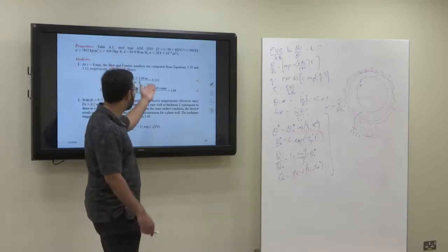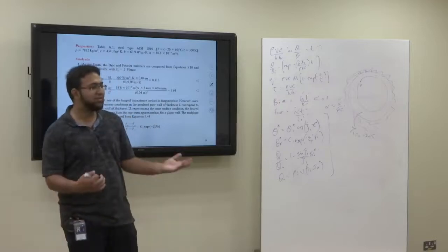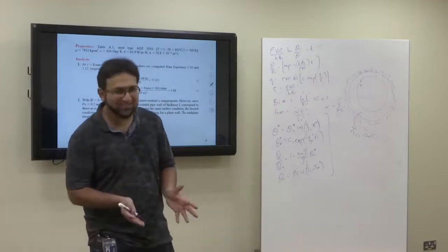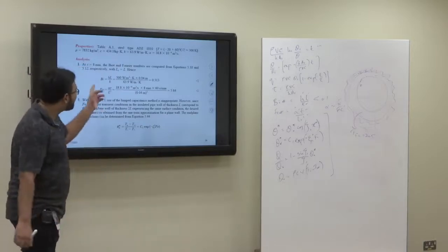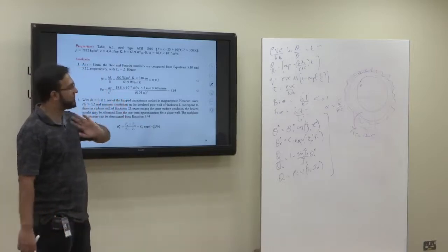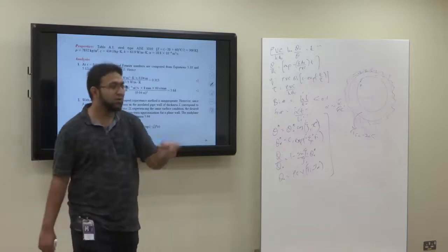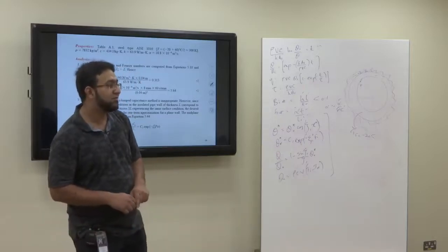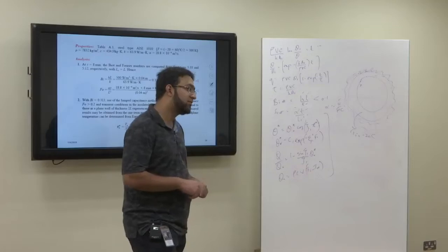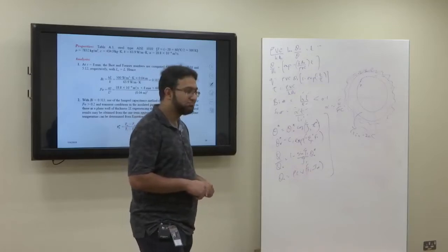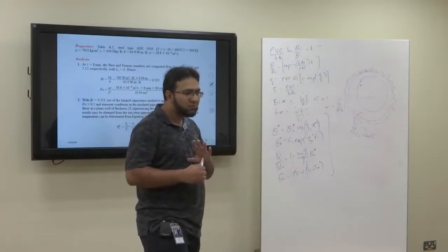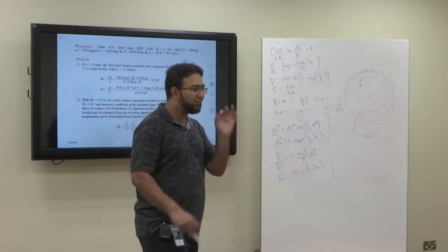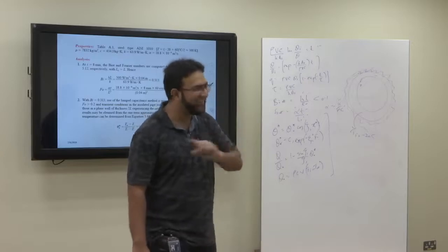There's a Biot number 0.313. I was hoping that we get less than 0.1, so our life gets a bit easy, but unfortunately, this is how life is. So our Biot number is 0.313. That means lumped capacitance cannot be applied. Even if it's 0.1, you can apply. But 0.101, no.